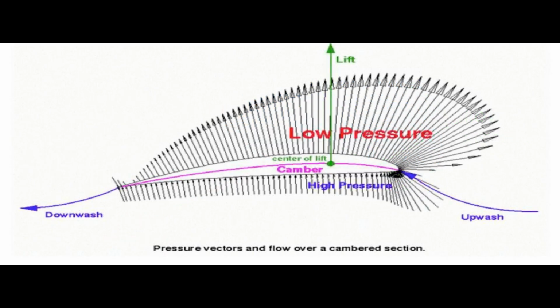A certain amount of lift is generated by pressure conditions underneath the airfoil. Because of the manner in which air flows underneath the airfoil, a positive pressure results, particularly at higher angles of attack. However, there is another aspect to this airflow that must be considered. At a point close to the leading edge, the airflow is virtually stopped, the stagnation point, and then gradually increases speed. At some point near the trailing edge, it again reaches a velocity equal to that on the upper surface.